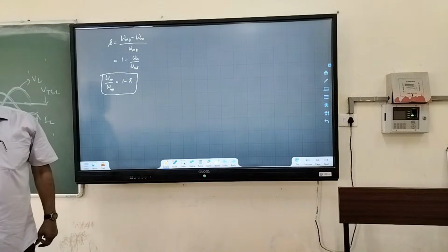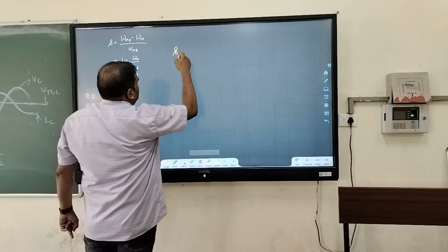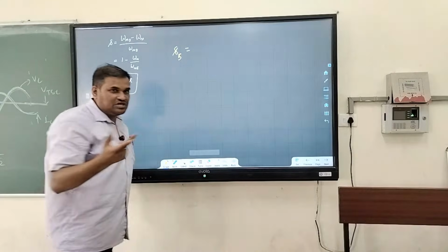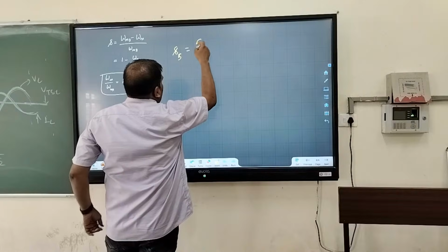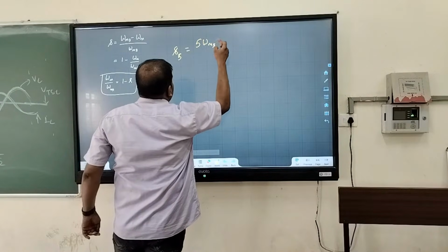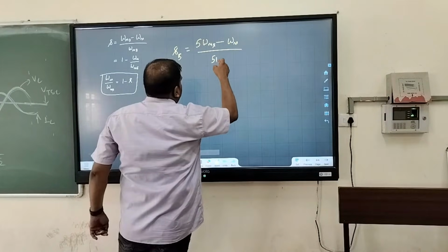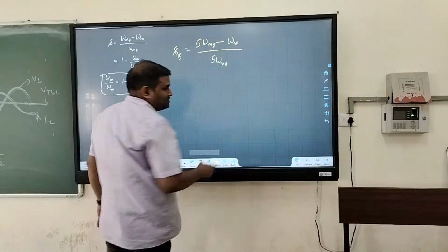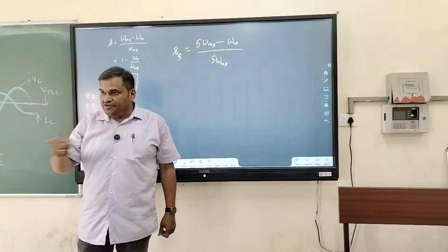What next is S5. What is S5? S5 will be 5 times the fundamental frequency. Instead of omega ms, I can write 5 times omega ms minus omega m divided by 5 times omega ms. But we also know that this omega ms is negative, reverse.